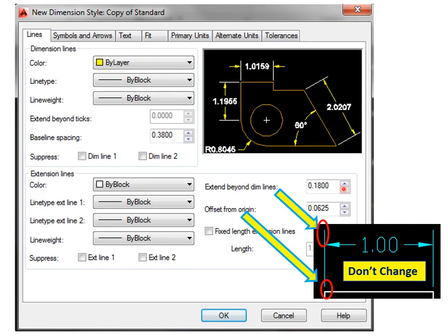Okay, another thing I wanted to point out here is, again, we are in the Line tab. These are already set for you. If you want to change the length of the extension lines, how they extend beyond the arrowhead, here it's set. And again, there's no reason to change this. You just leave it alone. It's following a standard, whether it's American or international standards.